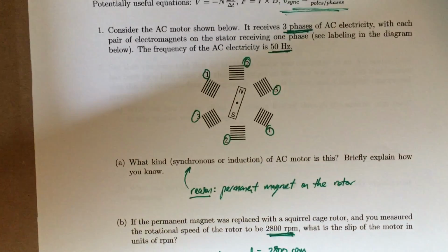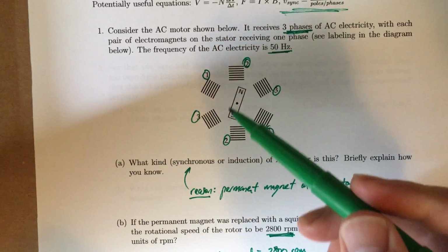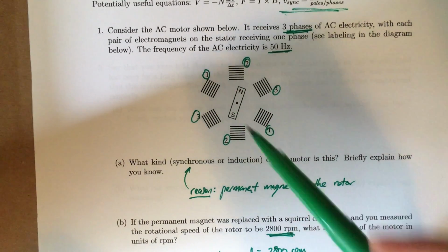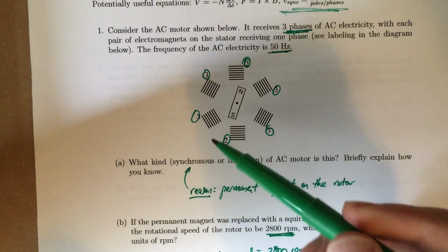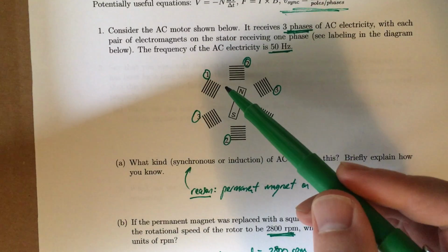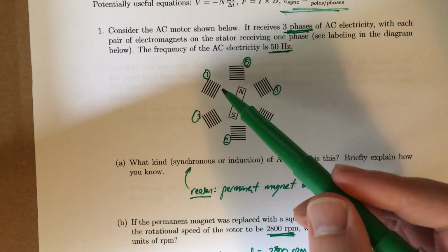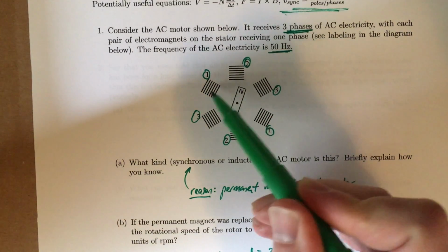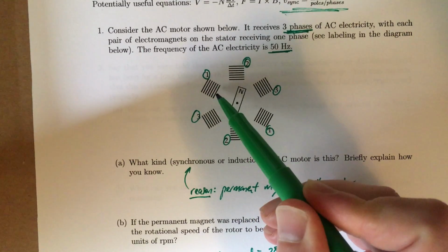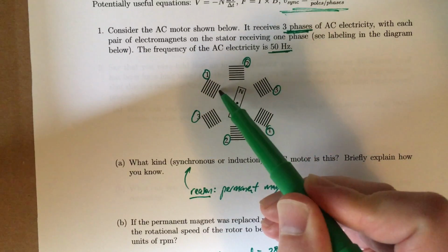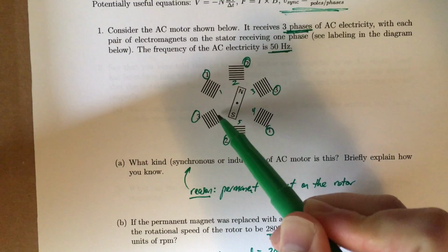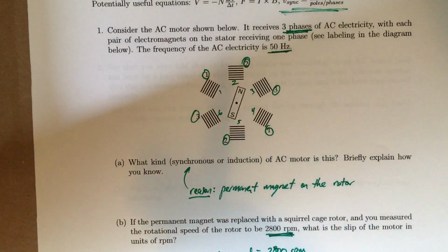Let's go back up there and count those. Right, for our definition of poles, and you can run into some alternate definitions where they sort of roll all this poles per phase stuff together. You see that in engineering literature sometimes, a lot actually. But because we've been usually just associating poles with individual electromagnets, I stick with that with our equation. So all we really need to do is count up the number of windings here, and we've got 6. 1, 2, 3, 4, 5, 6.